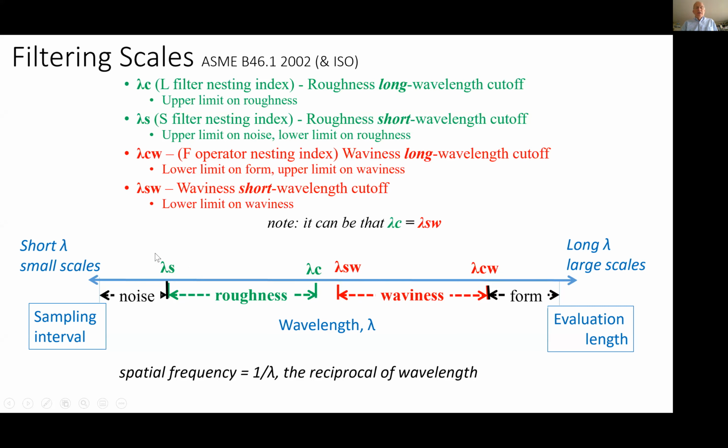Now waviness, the one thing that I've heard that waviness is a good predictor of is noise in bearings. So this is at a larger scale. The roughness can be very important for holding lubrication, say in bearings. And so these are effective in some things, particularly in the automobile industry, in sorting this out. That's because the automobile industry had so much impact over the development of standards, particularly coming out of World War II, when a lot of this stuff got developed, particularly in the United States.